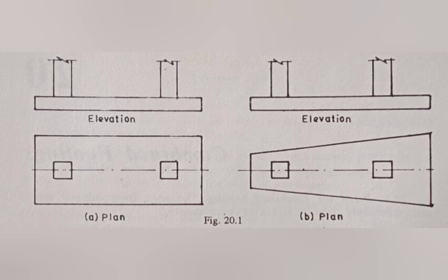If the footing is to support an exterior column at the property line where the projection of the footing is limited, a rectangular shape can still be used provided the interior column carries greater load.